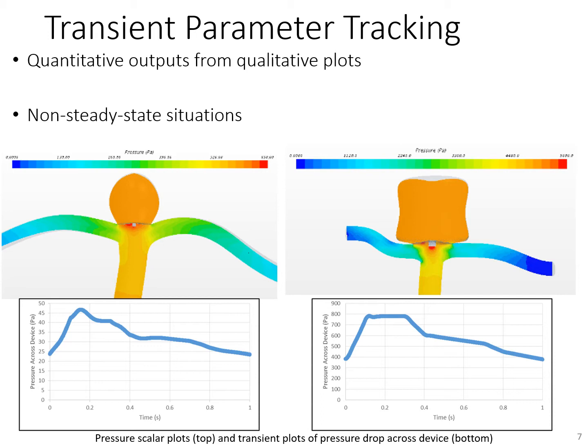This output allowed the research team to verify and validate their numerical calculations and estimations in a non-trivial bifurcation flow system, where significant energy is lost at the bifurcation compared to a typical straight line flow jet calculation. This analysis also demonstrated how the parent vessel geometry feeding the blood flow toward the aneurysm likely plays a significant role in the amount of force applied to the device, as a smaller vessel would tend to generate higher velocities focused at a smaller cross-sectional area, leading to increased stress placed on the device.